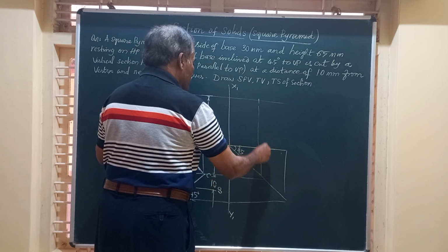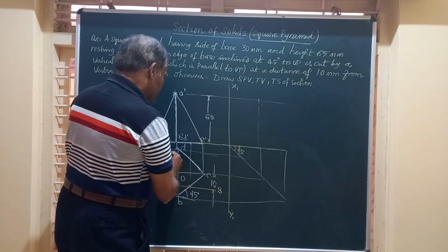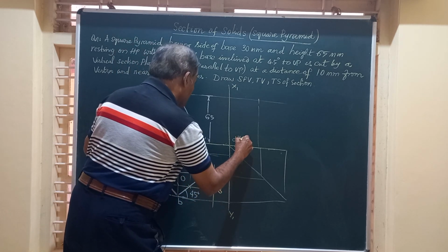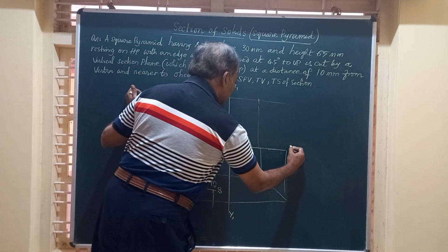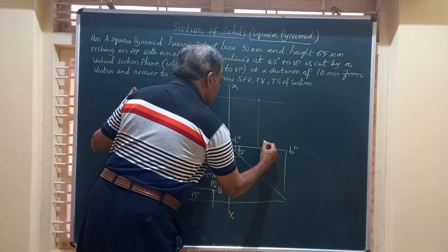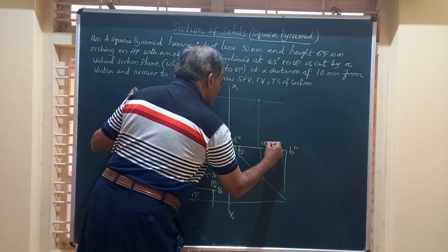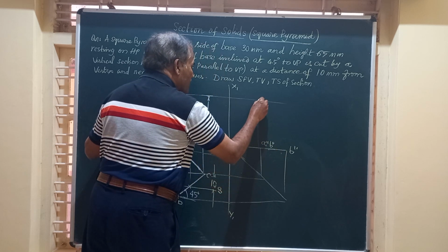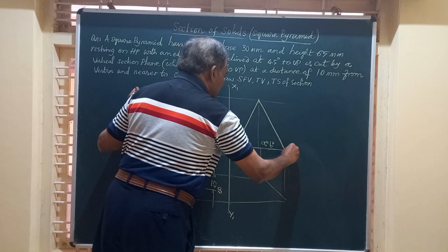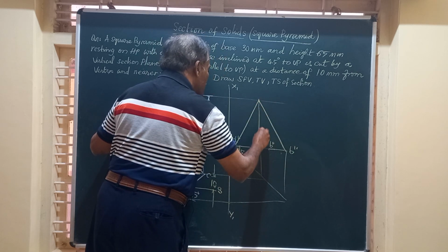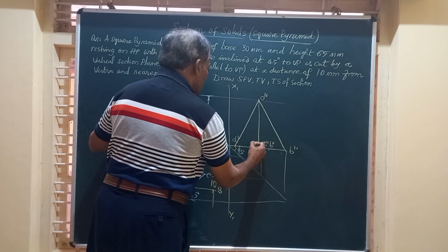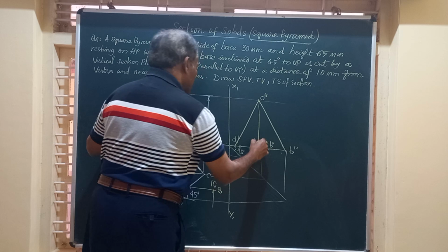So this is going to be the side view. So this is point D double dash in the end view, and this is B double dash on the other end, and here you got A and C, A double dash, B double dash. Friends, you got all the 4 corners of the base, join them by straight line. This is how the object looks in the end view. This is all double dash, O double dash, and this is O1 double dash.